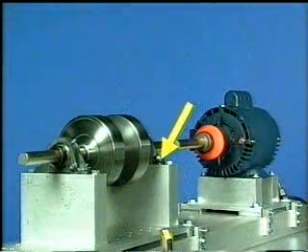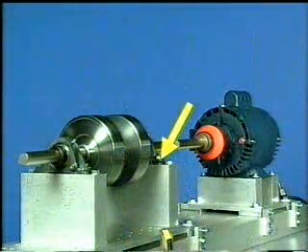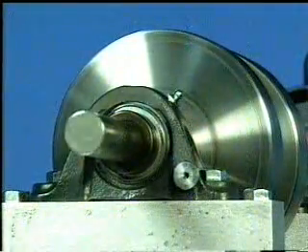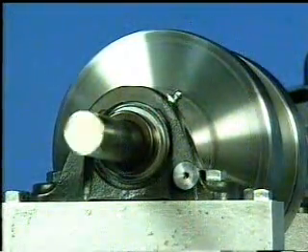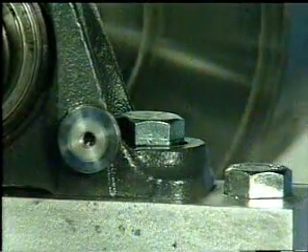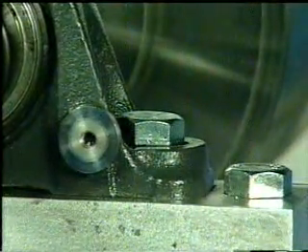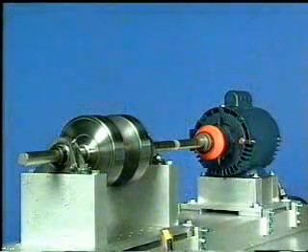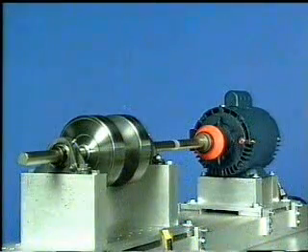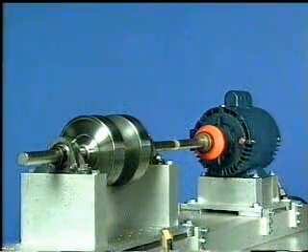Because the coupling is pulling on the shaft, the feet closest to the coupling act as a pivot point. The location of the feet relative to the measurement point then affect the vertical or horizontal readings across the couplings so that they may be in phase or out of phase. In all these alignment measurements, be sure to allow a 30-degree difference for determining in phase and out of phase conditions.